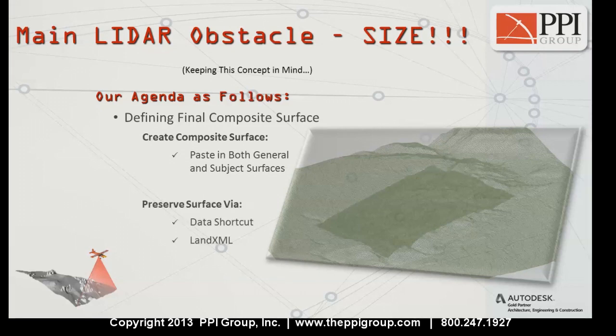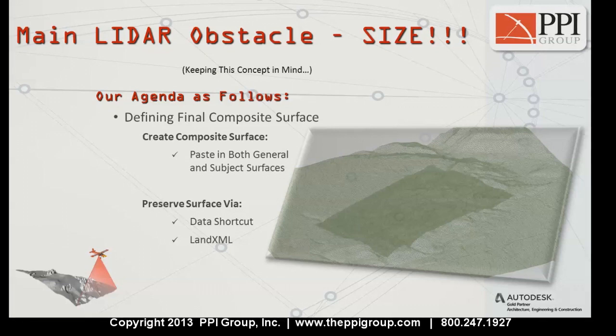And then once that's actually comprised, this information could either be kicked out through data shortcuts, or for that matter, using LandXML. You could start a completely unrelated drawing and then bring this data in. So now we have a very, very clean and precise surface created from all of this data.